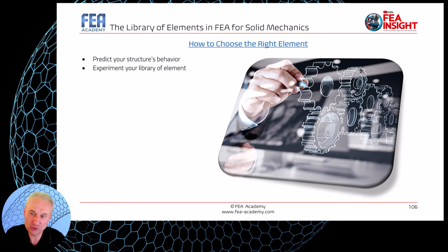Before beginning to build your model, make sure you understand all the capabilities and limitations of the elements that you're going to use. The problems can often be solved in many different ways, okay? But making a good choice can reduce effort, computing time, and errors in the results.